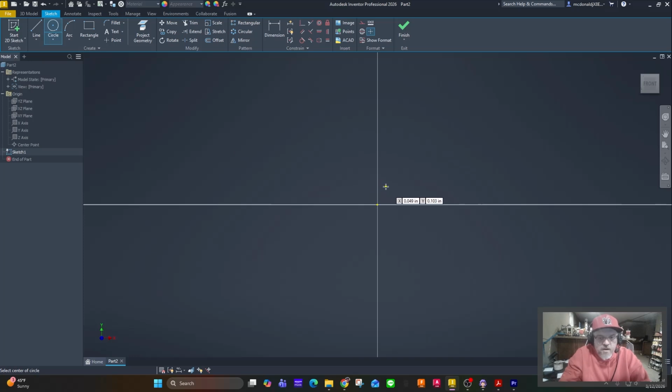Best practice is to always make something touching the origin, if at all possible. 3D models coming out of CAD software not only go to manual machinists, who can make a part without knowing exactly where it is in the XYZ coordinate plane, but they also go to CNC machines, so computer numerically controlled.